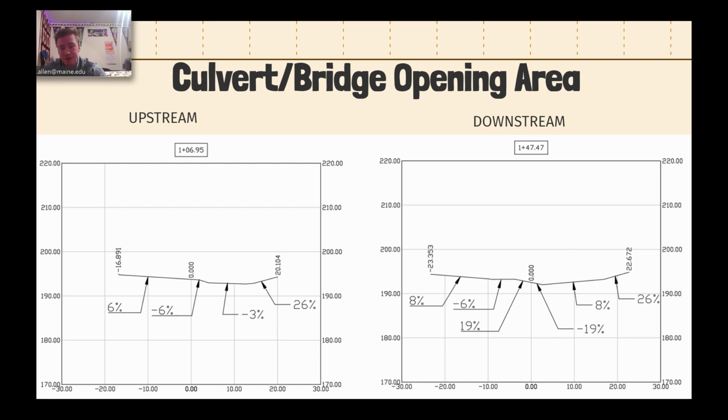In order to create a cross section, we took 5 points. One on the upper left bankfull width location, a second where the water's edge begins on the left, a third from the middle of the stream, and then 2 more at the water's edge and the upper bankfull on the right side. This process was done at 2 locations upstream of the Mount Pleasant culvert, 50 feet and 100 feet back from the opening. These cross-sectional points were calculated, and the horizontal distance between these points was used to determine this value.